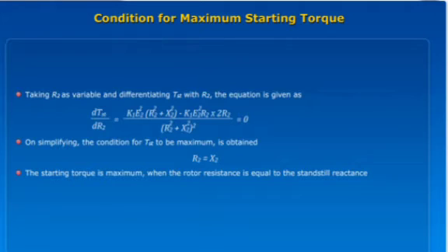The working range of the motor is hatched. The range of slip is from 0 to 0.05. When s is more, the rotor copper loss will increase. Rotor copper loss equals rotor input into slip. Therefore, values higher than 0.05 are not preferred owing to increased copper loss.